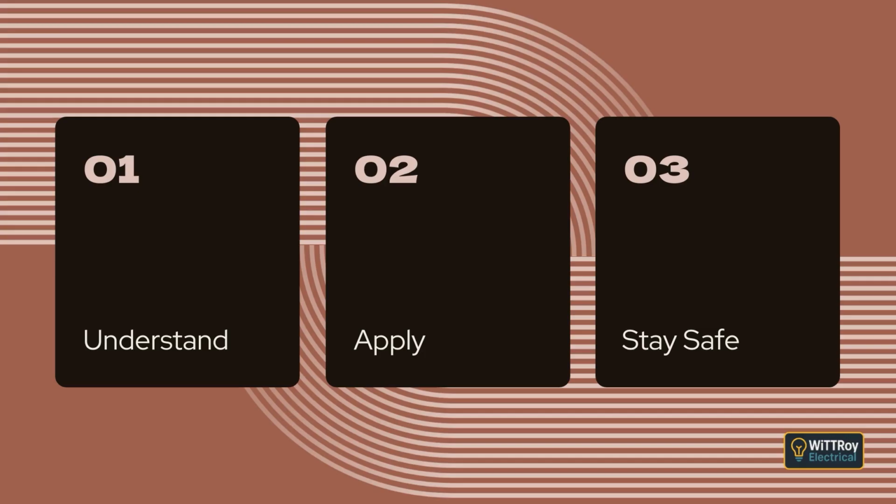A main or isolating switch must be installed on the switchboard inside the outbuilding, and it must be able to isolate all supply to that outbuilding. If the outbuilding has more than one submain supplying it, each submain must have its own isolating switch. These switches do not have to be beside each other, but clear permanent notices must show where each switch is located. This prevents a person from thinking they have isolated the building when another supply is still live.